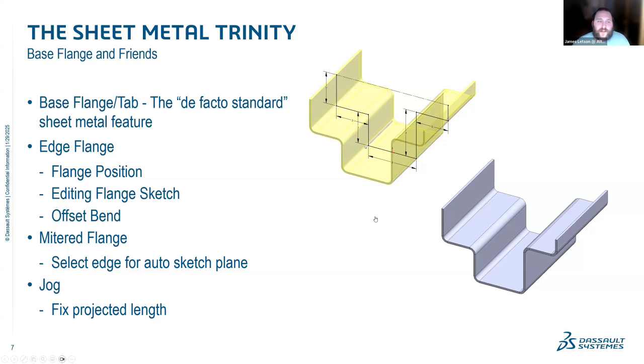But there are a few things within the base flange and friends category that I want to talk about. Edge flange, there's a few different tools within the edge flange feature that I want to touch on. I'll touch on mitered flange, and then I'll touch on jog, just because those I feel are some lesser known base flange and friends tools, right?